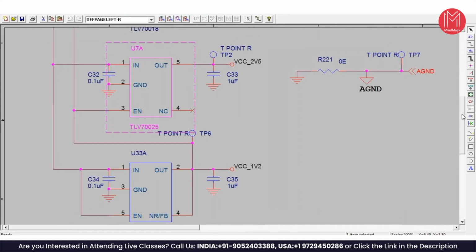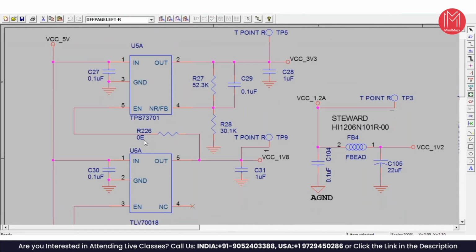For the first one, enable to the second one's output, you have connected one resistor, right? But in the rest, why do we have to connect that resistor? Yeah, it's a 0 ohm resistor. So basically, when the schematic was given, in case you want to disconnect 3.3 volts, this is given to enable or disable the 3.3 volts, but it's really meaningless. You can connect it directly.